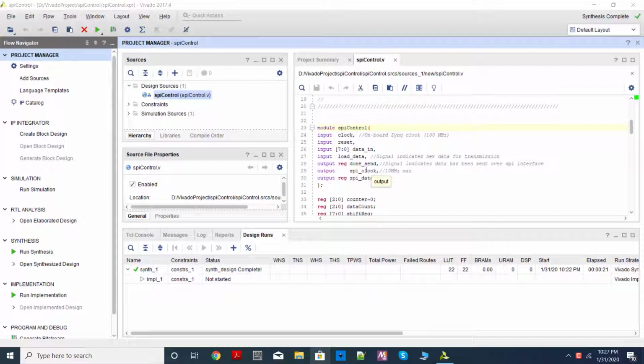But if you have access to some oscilloscope, maybe you can hook it up to the FPGA and see how the signals are changing. But Vivado and the Xilinx FPGA have a very powerful feature through which you can actually see signals in real time on your computer. Okay, so that's what we are going to see today. Now, this application is not only for seeing the output signal, you can see any internal signal in your design during runtime, and this is very useful in debugging.